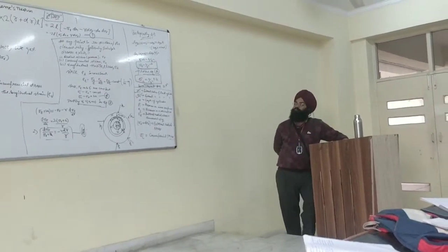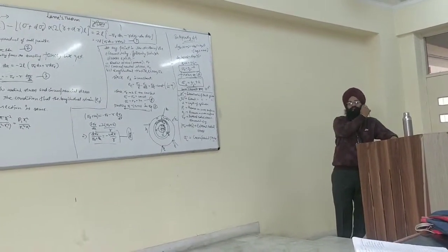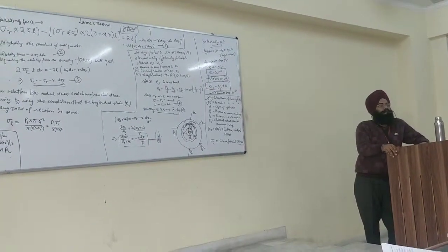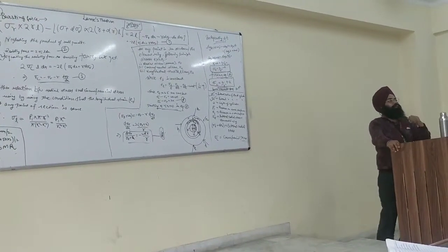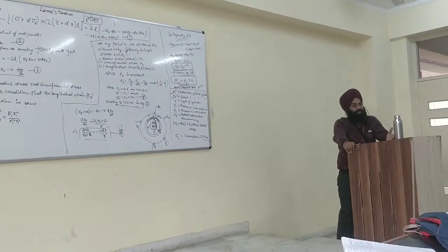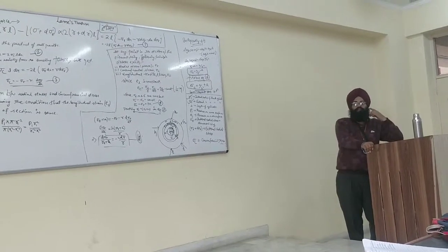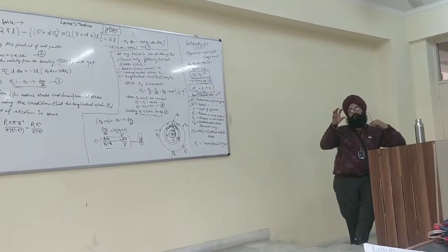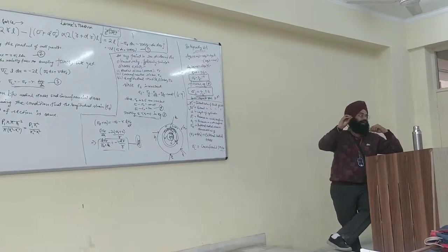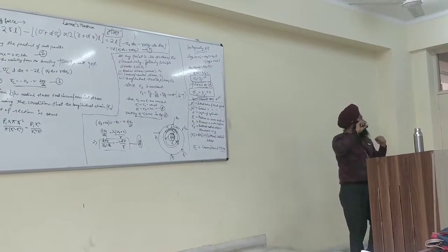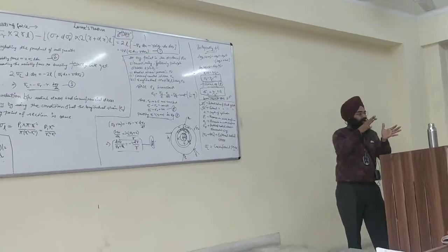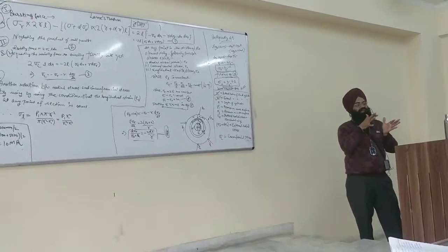What is this Lame's theorem? We will go through the definition and derivation of it. In Lame's theorem, we have a few assumptions that we need to set out before we do the derivation. First, if we introduce the internal pressure fluid inside the thick shell through the internal diameter, there will be no change in the external shape of the thick cylinder.